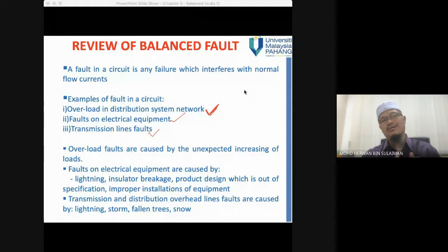That's why when you learn about electrical power systems, the flow of knowledge is: you learn about the components of the power system, next the load flow, and then the fault analysis, because the fault analysis will be used when you want to decide the circuit breaker. After this, you learn about the protection of the power system, that includes how you set the relays, the relay coordination, and so on. So that is important.